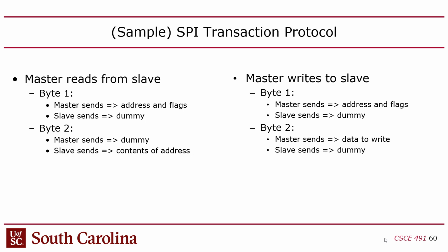So it requires 2 exchanges bundled together in one communication session, meaning that it's 16 cycles of slave select being down in total, right? Now that's kind of a minimum. In practice, you may have to do more than 2 bytes, two exchanges. But this is kind of the baseline version of it.